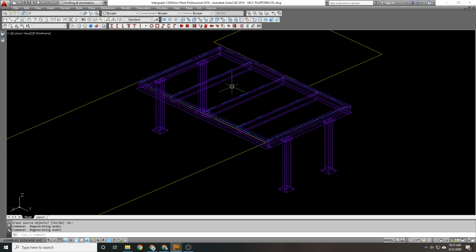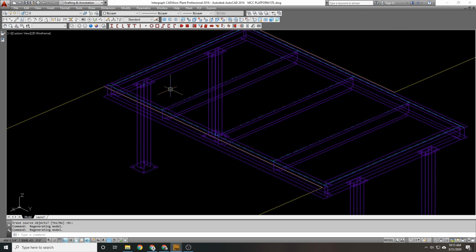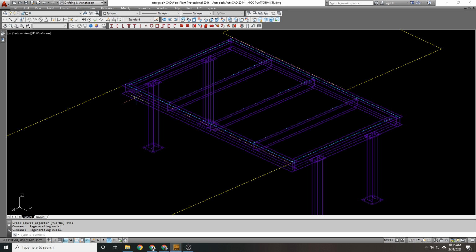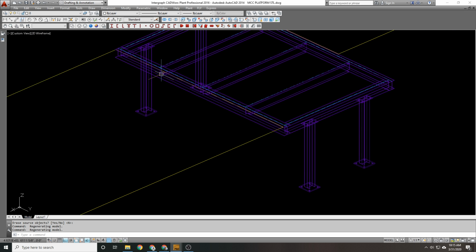So now what I don't know yet, now that I'm looking at this, usually this is how it works. I'll start with the initial design and start to tweak it after the fact. I can see about keeping it like this, but if I do this way, without having a beam go between the columns, I won't be able to do any kind of bracing. And I'm almost positive that the engineer is going to want to see some bracing, because now this long direction is in the weak axis because of the way the column is turned. And he's most likely going to want bracing in this weak axis and just the length of the span.